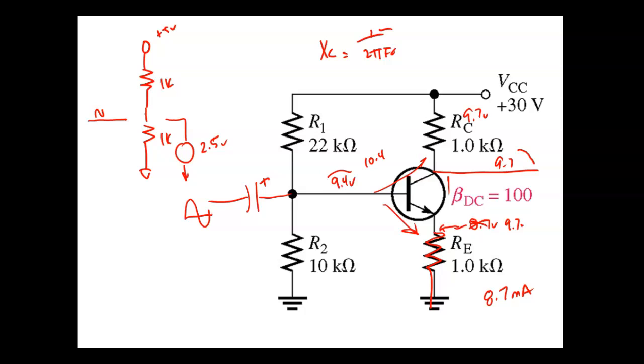But we'll use a beta, and the problem is when we calculated this voltage drop right here, why did we ignore RE? Well, that's determined by beta, right? We'll look at that in a minute. Why can we ignore RE, even though we have a path for current flow to get to RE? Yeah, we're going to get to it. How can you calculate RE to R1, R2, anything over RE? Well, we know RE. We know that if it's a silicon transistor, the difference between VB and VE is going to be 0.7 volts.